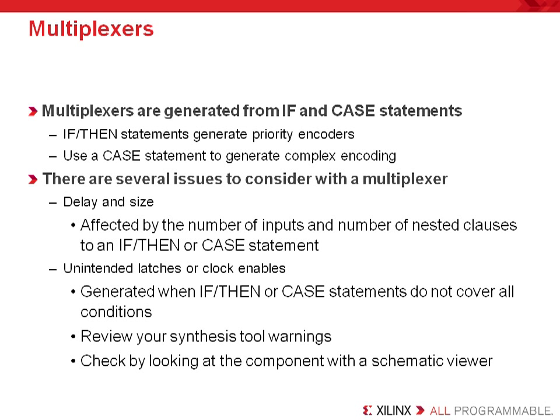So if you build a mux with if-then statements, note that the timing critical signal, that is, the signal on the first if statement, ends up in the last logic stage. This signal will have to go through only one logic level and have the shortest delay. This is perfect for the case when you need one of the inputs to be faster than the other inputs.